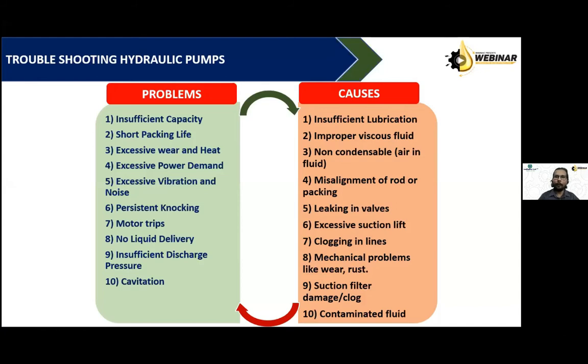One is what input we are giving, that is our fluid, and where the fluid is exposed. Suppose our system was designed for a temperature around 65-70 degrees Celsius, and if it is exposed to 100 degrees Celsius, definitely a problem will come.